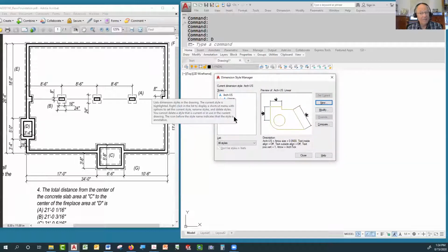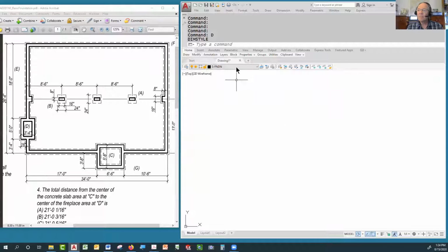Now, for an actual template file, I'm going to have to go back and add more to this. But for this drawing right now, I'm happy. I'm going to close this out. Now, I've got S-FND as my foundation layer. I'm going to change my limits now. And the limits, I'm going to make them large enough for when I'm drawing. So the lower left-hand corner is 0, 0.